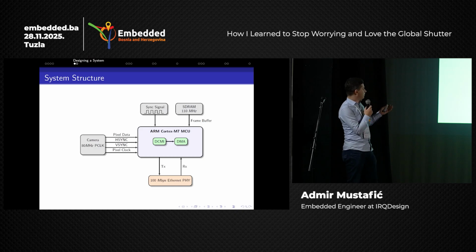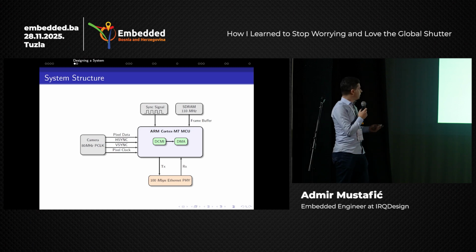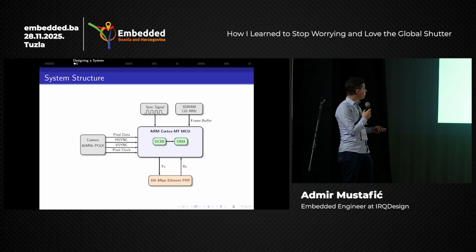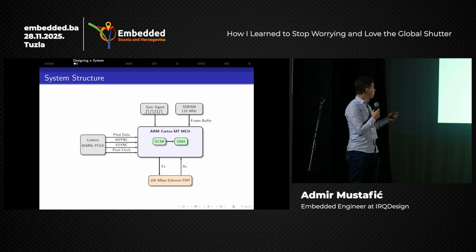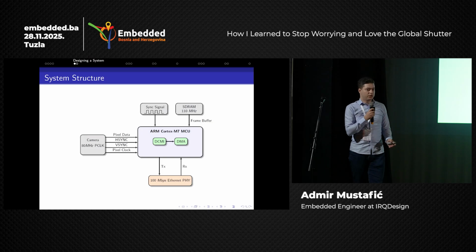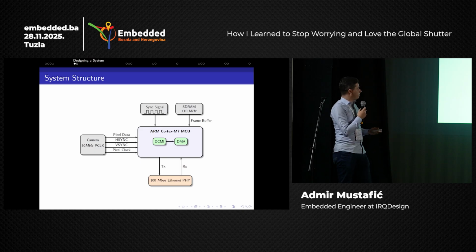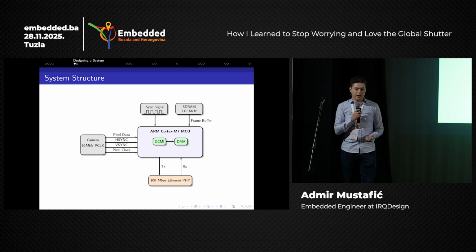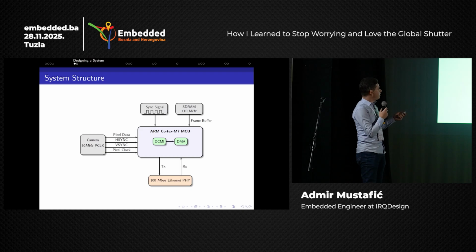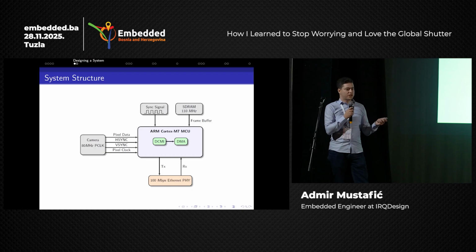We have the digital imaging sensor, or our camera, which also has that capability to be coupled with the DCMI peripheral of said microcontroller with the pixel data lines, the parallel data lines, the horizontal synchronization, vertical, and the pixel clock itself. The storage of the data itself needs to be also really fast in order to ensure quick and fast capture, so we do not miss any frames. In that regard, we use the DMA coupled with DCMI and some external memory.